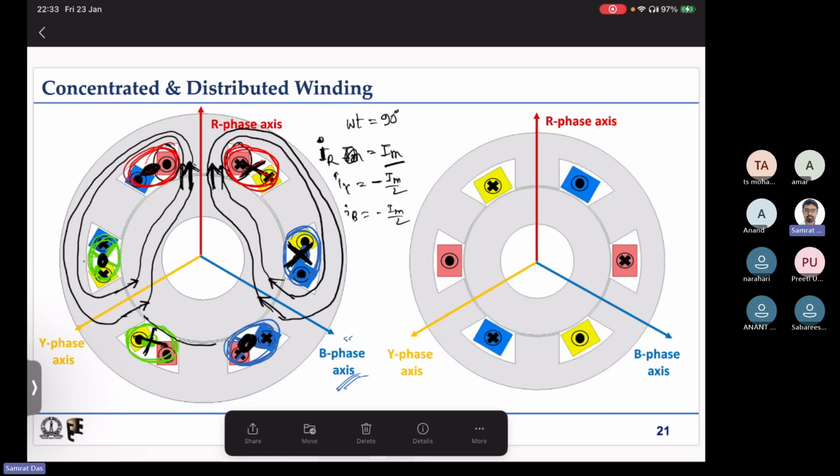If you put some rotor bars like that, similar to an induction machine, there will be some induced EMF because there is a change in rate of flux linkage. They may or may not be sinusoidal. There may be more ripple, some more noise, but it will run at least.